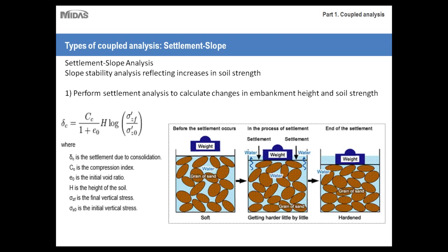So that's another key thing to keep in mind: when clay is consolidated, first and foremost it compacts, so there's displacement, and second, the overall strength of it is increased as well. Because of these factors, that could affect certain analyses you may need to run for the structure itself, as well as, for example, a slope stability type analysis, which we'll be discussing here.